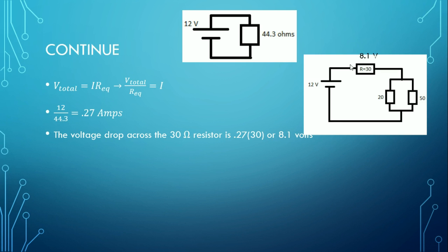So that's quite a bit of the voltage, about 66%. Now if we use the loop rule, we know that in a loop, the voltage equals 0. If we make the loop clockwise in this case, and the current we know is clockwise, batteries are positive, resistors are negative. If you are not sure why that's true, just look at the last video I made, where we talk about the loop rule, if you want more practice with that.